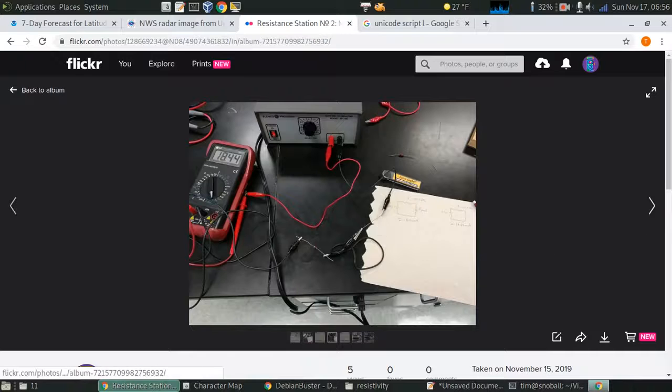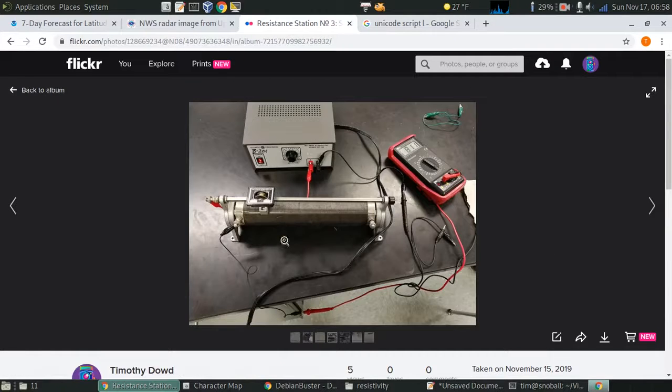But we do actually have a device called a slide wire rheostat, which was specifically made for adjusting the resistance and varying it by altering the length of the conductor that current is flowing through. So we could do some experiments with this to at least check the effect of length on resistance in a quantitative way.